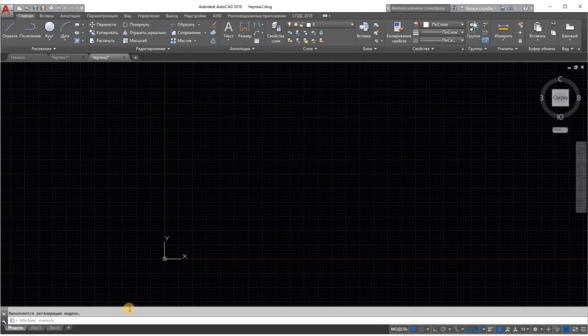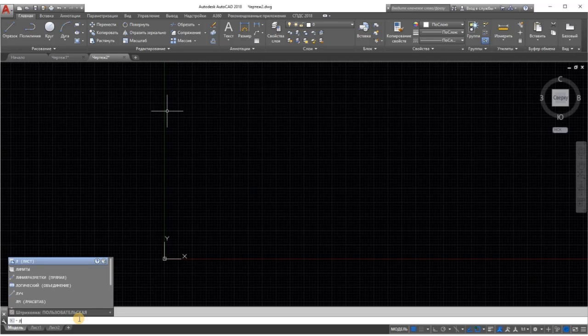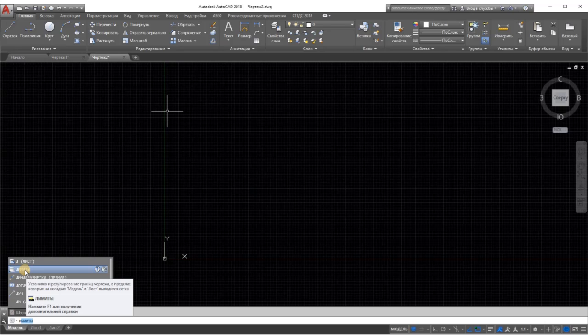You'll start by setting the size of the work area, known as the drawing limits. These limits aren't fixed in any way, and you aren't forced to stay within the bounds of the drawing limits, unless the limits command's On or Off option is turned on. But limits can help to establish a starting area from which you can expand your drawing.